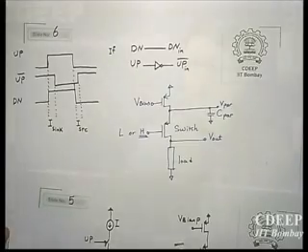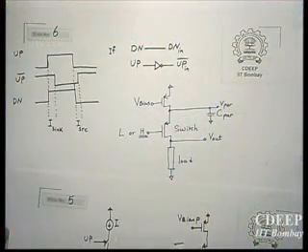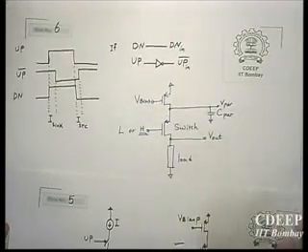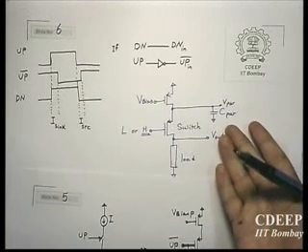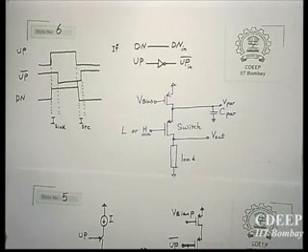As it approaches VDD, the current source enters into its ohmic region. Therefore, it won't be a current source anymore. And because it's not a current source, it will stop operating as a current source. And in fact, finally, even the current through this resistor will stop because this capacitor will charge to VDD and then it will stop. So now you don't have a current source anymore.